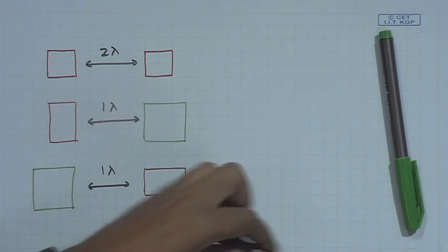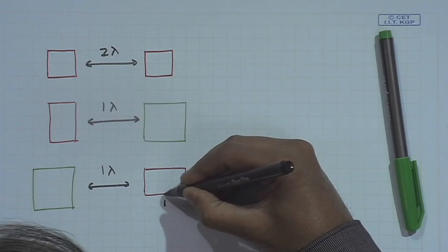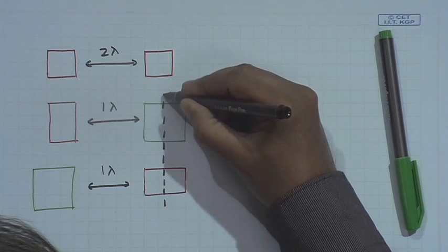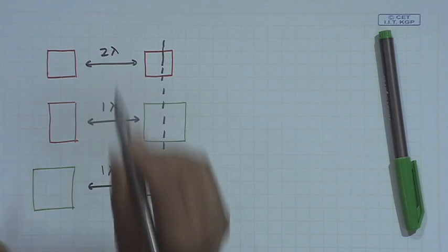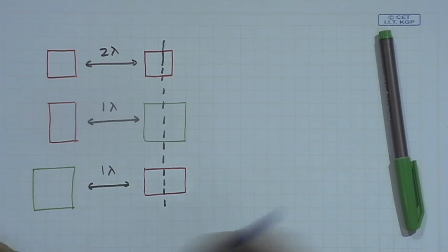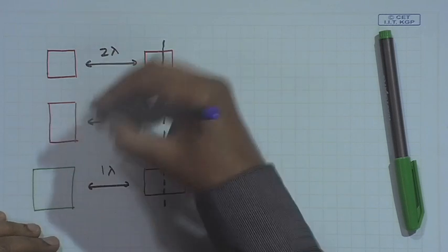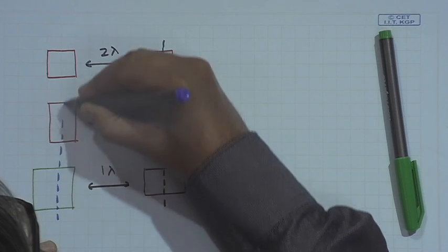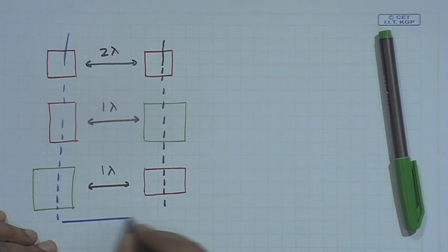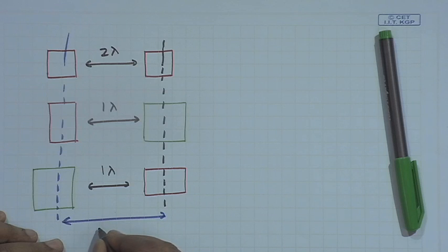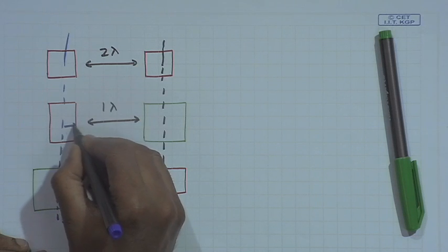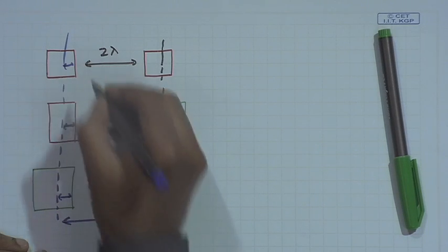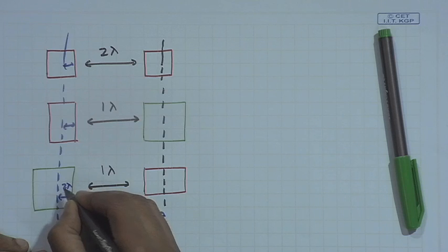Now, when you are attaching a grid to these three, let us say, so what you can do? But in the actual case, let us say this is the minimum constraint, but what you find in this layout is that with respect to these two grid lines, let us say this is a grid and this is the other grid, the separation between the two grid lines is, let us say, 8 lambda, and this part is also something, let us say these are all 2 lambda each.